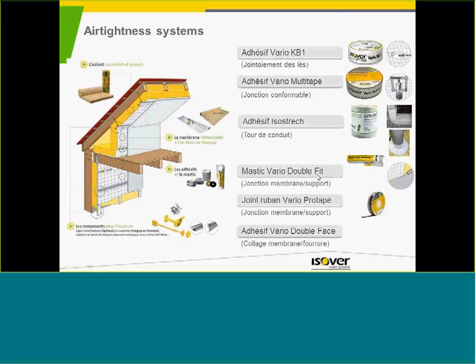And to finish, we also have mastic, which is able to do the junction between the membrane and the different supports like concrete, metal, and other types of support, in comparison with the adhesives, which are here to do the junction between the membranes only.